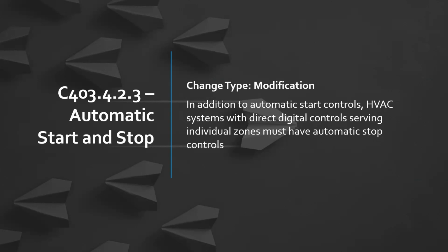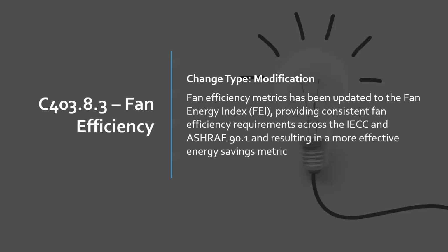I appreciate that, Ben. And so just these automatic starts and stops, you've got to have these controls. Again, it goes back to the lighting part of it, the HVAC part of it, the mechanicals part of it. That's one thing. The second thing is, is it commissioned properly? Does it function? Does it actually do what it's supposed to do? Does it have the setbacks? It needs to be tested to make sure that it actually functions properly to meet the requirement of the code.